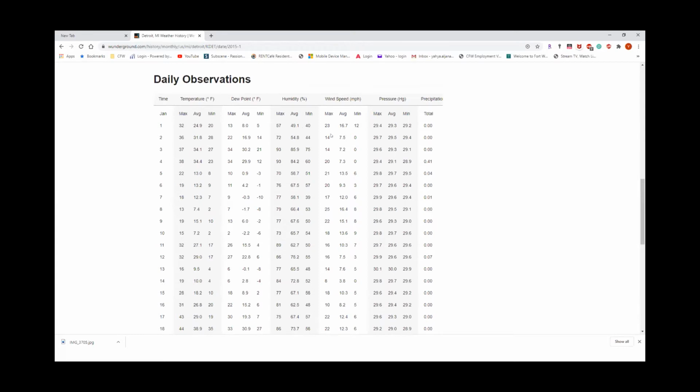Also, the wind speed will affect the hauling and the structural steel work. If it's passing, I would say, 20, that's based on OSHA. And again, this also goes to the crane specification. It could take more than that, but just as an OSHA requirement, we would say 20.